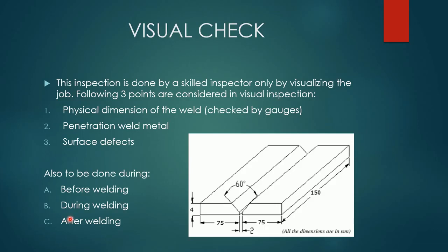Now before welding means the surface is checked for contaminations like dust, oil, grease, and scale. The cut edges are checked carefully for presence of burns. So before doing welding, the gap, the groove surface, all these surfaces are required to be cleaned enough.